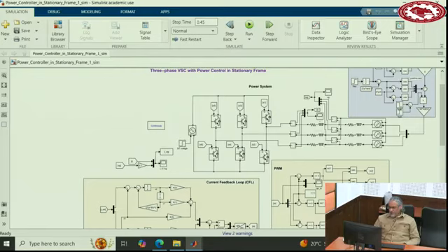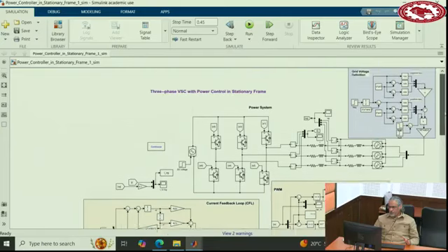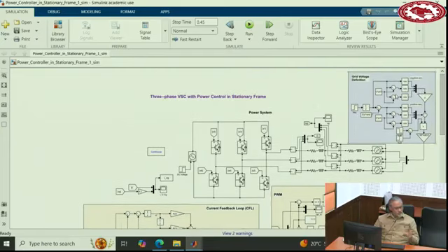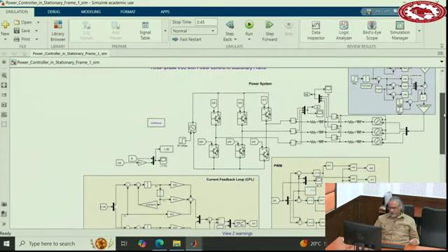On the AC side, we have a three-phase filter, and this is the point of connection. Then we have an impedance that models the grid impedance, and this three-phase voltage really models the voltage behind the impedances. These are controllable voltage sources, and you program how you want the voltages to change. If you want to apply harmonics or negative sequence or faults, you can program all those things here. Make it unbalanced, balanced, and so on.